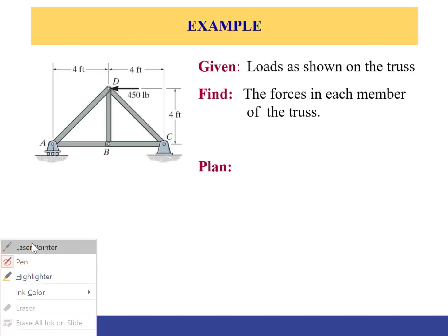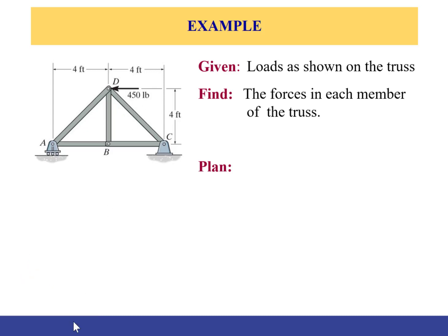Okay, so let's take the following question or problem. So we have a simple truss. This is a simple truss system. It follows the simple truss requirement, where if you start from A, D, B, and then you can continue building the truss by adding two elements at a time with one common joint, which is C. So this is simply a simple truss.